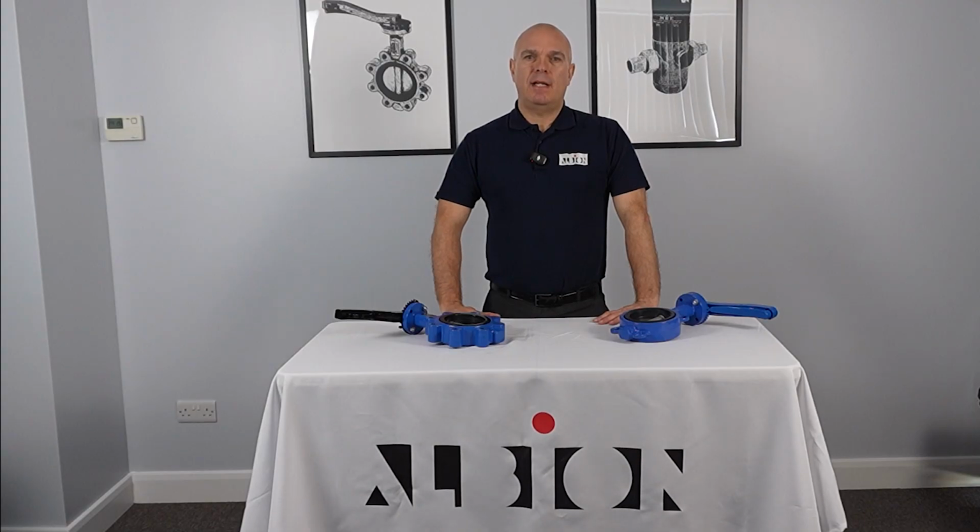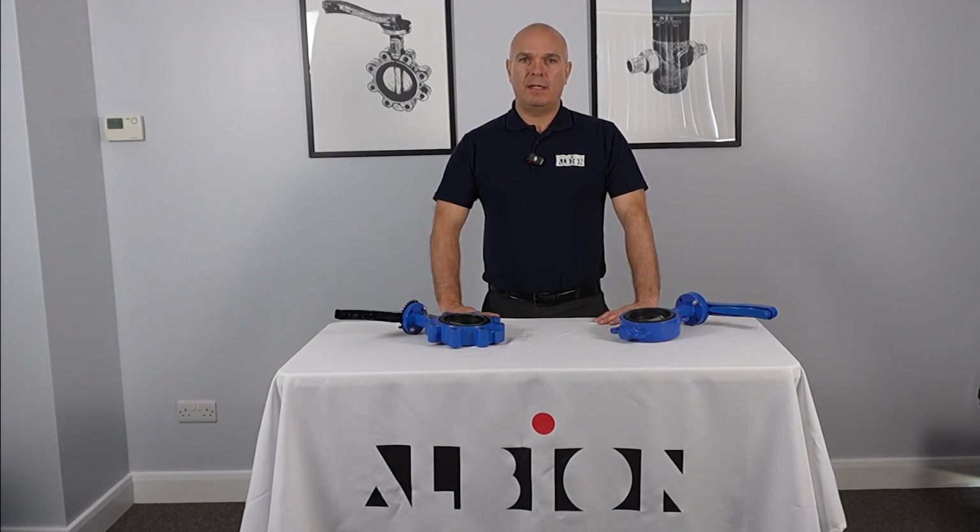Some of the valves within Albion's range of butterfly valves come with WRAS approval and can therefore be used on drinking water systems. All polymers that come into contact with water on these valves have a BS 6920 approval, so can also be used on applications that are governed by the Drinking Water Inspectorate. If these types of approvals are not required, and you require a valve for a heating or cooling system, or even a gas application, you can rely on Albion to be your trusted partner.